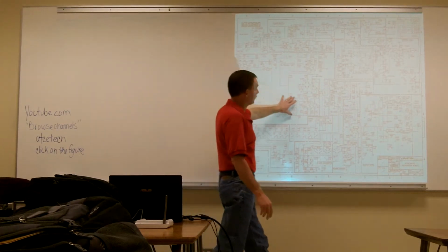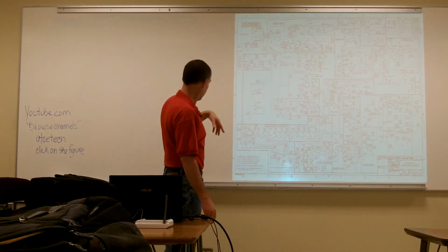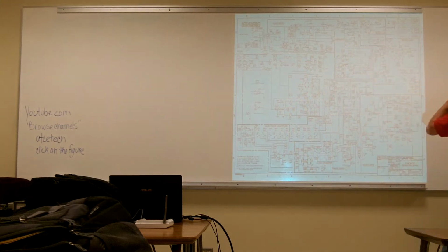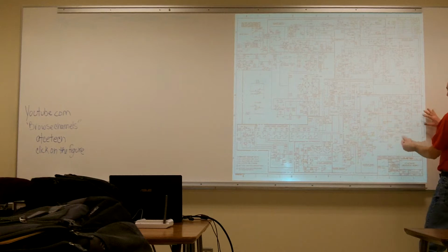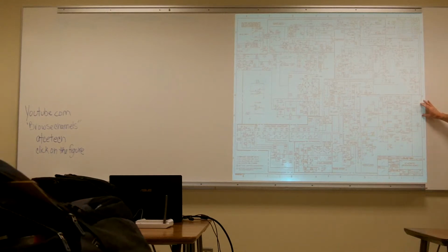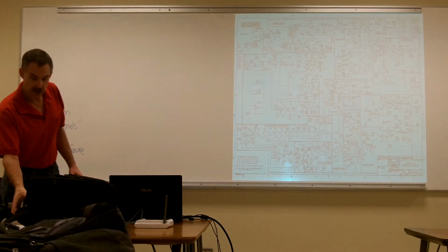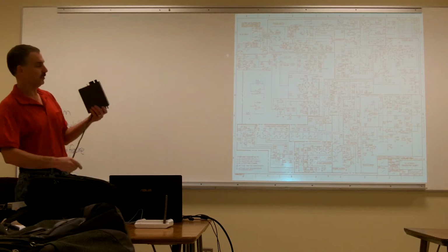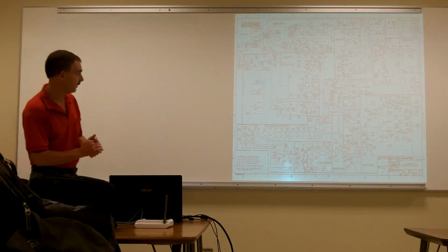Then we have different functions on it for setting up the different frequencies and our amplitude and stuff like that. And on our output, right on our connection where we hook it up to our circuit, this is our output. So from here to our power supply, including all the circuitry, we'd have about a 50 ohm impedance. On a function generator you have about 50 ohms, and on a regular DC power supply, it's down to less than 10 ohms.